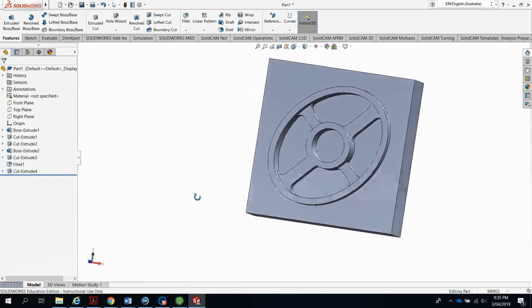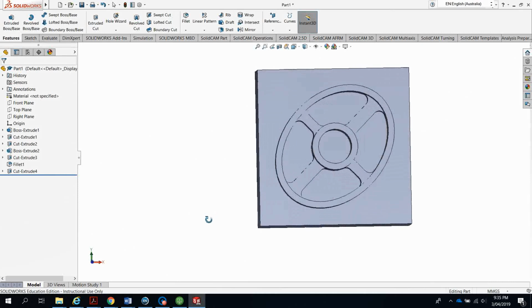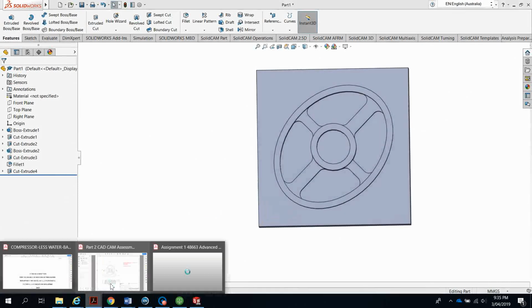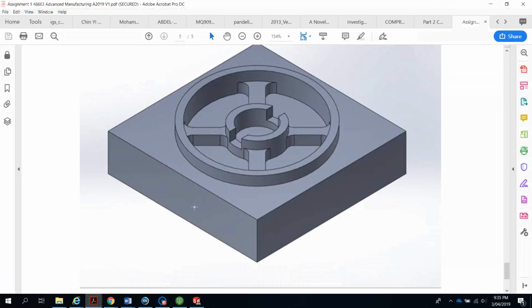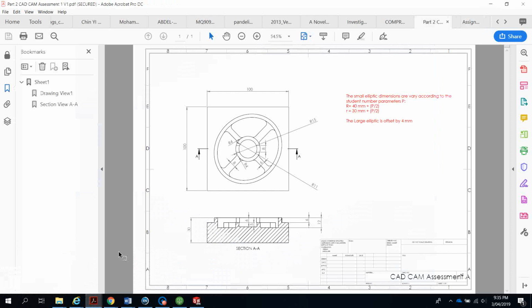Now to make the slot cutting on the cylindrical shape. You can see that this one is actually just going to be horizontal across the AA section. So this shouldn't be a hard task, and its depth is going to be equal to 6 at the same time.